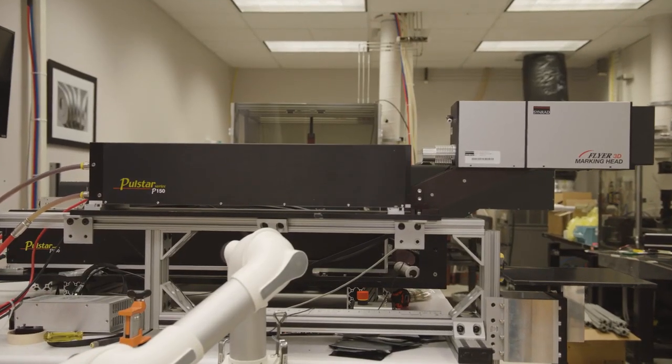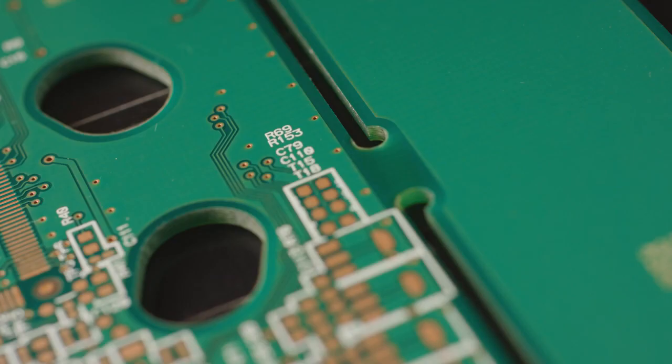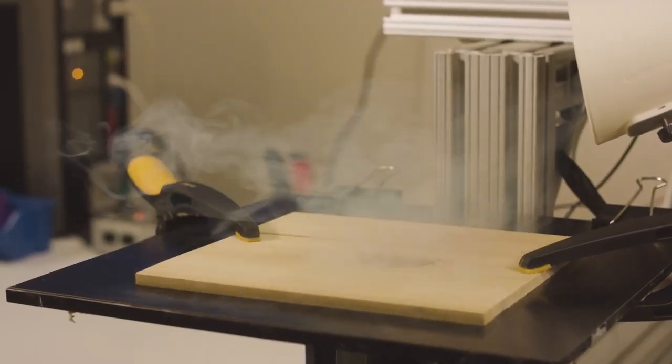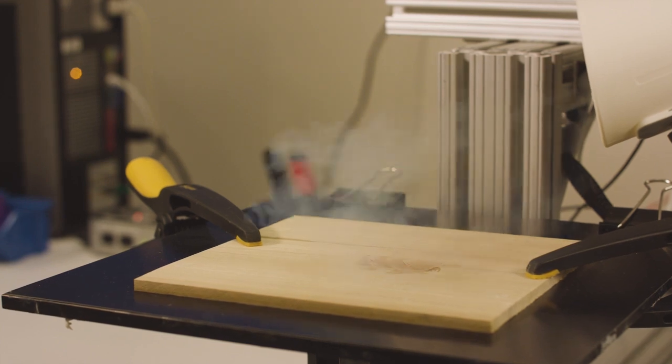Scan heads use galvanometer mirrors to quickly steer the laser beam across a material. 2D scan heads are often used to create small detailed marks, while 3D scan heads incorporate a third, Z-axis, to allow fine processing across a wider field of view. Cinrad scan heads are available in both options and are pre-aligned for quick plug-and-play use.